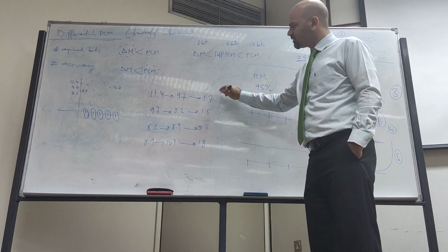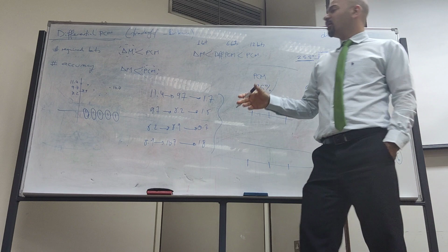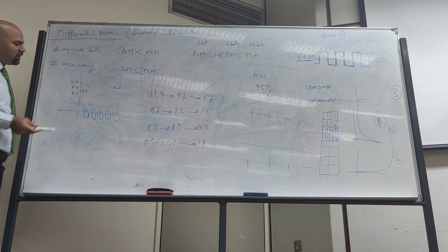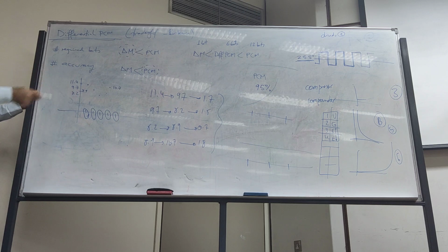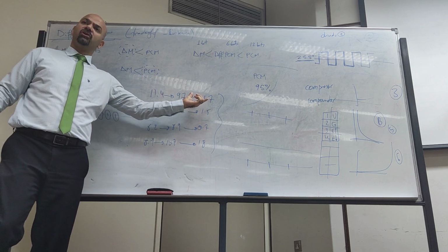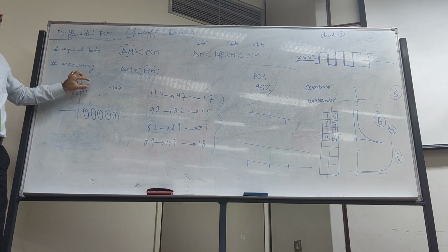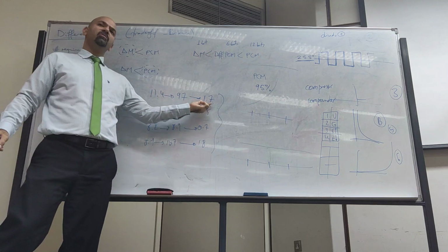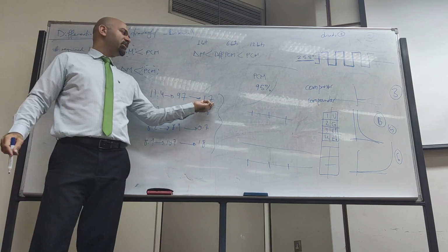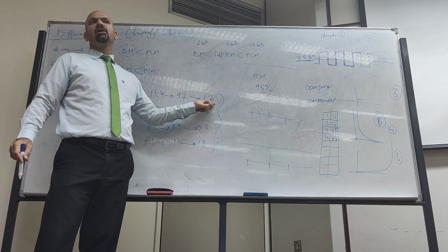You see the changes? The range for the changes is between 0 and 2 maybe, while here the values are between, I don't know, 0 and 11.4 or 8.2 and 11.4. So if we encode the difference, I will send the first one, 11.4, and then an increase or decrease of 1.7, an increase or decrease of 1.5, so the number of required bits will be less. Why? Because it's only telling the difference.